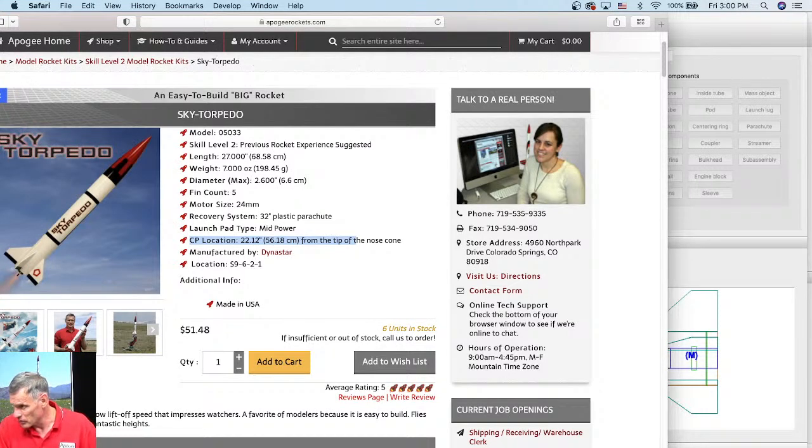Johan says, with an egg rocket, extend the shock cord to the rocket with Kevlar. One time the egg capsule banged into the rocket real hard after ejection and ruined the rocket. Okay, so what he's talking about is nose cone snapback. If you have an elastic shock cord that connects it, this one has a Kevlar.